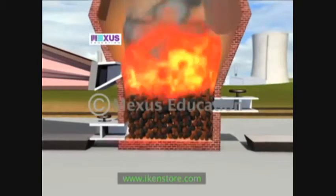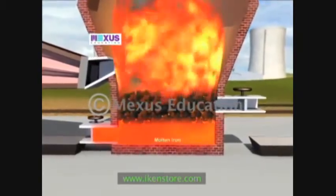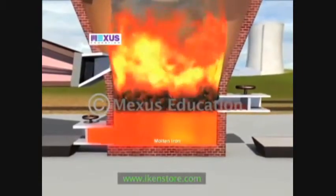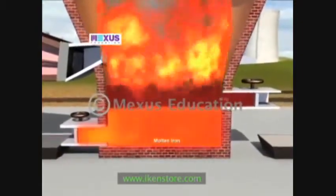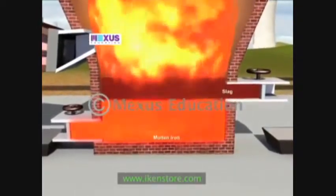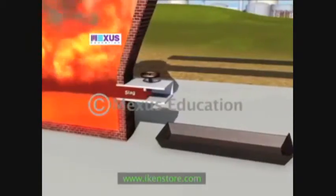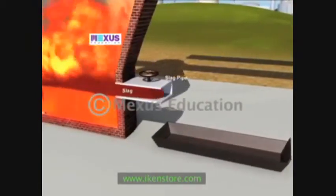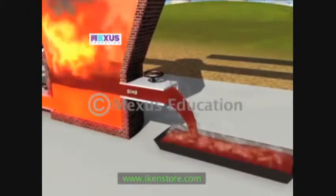As the operation proceeds, the mass in the furnace becomes molten and descends into the crucible. The iron sinks to the bottom. Impurities, called the slag, being lighter, float on the top. The slag is drained through a pipe in the upper portion of the crucible, which is called the slag pipe.